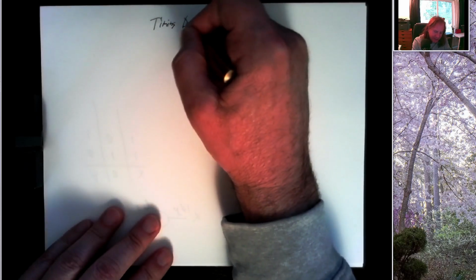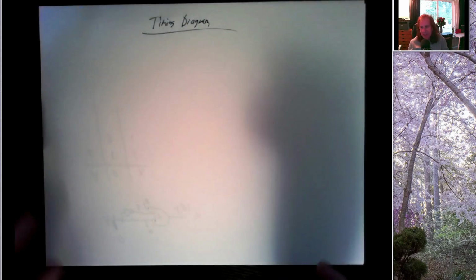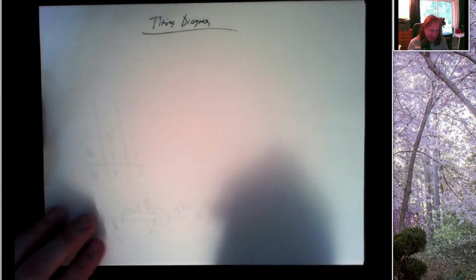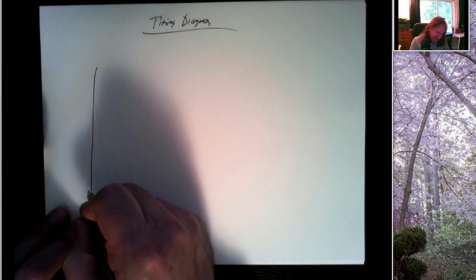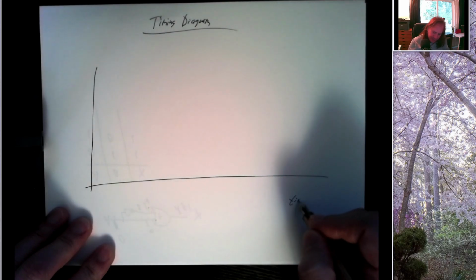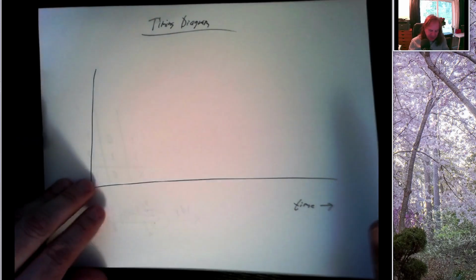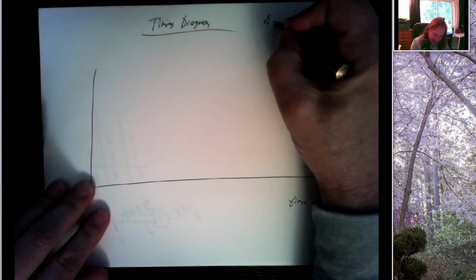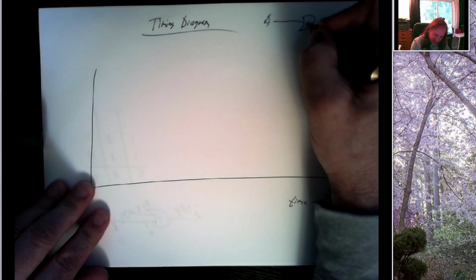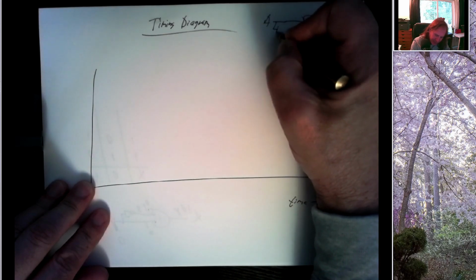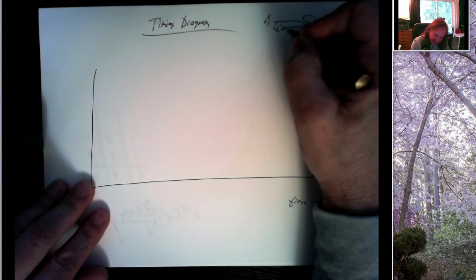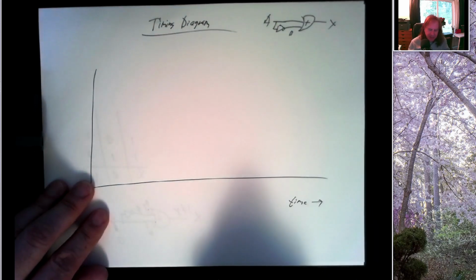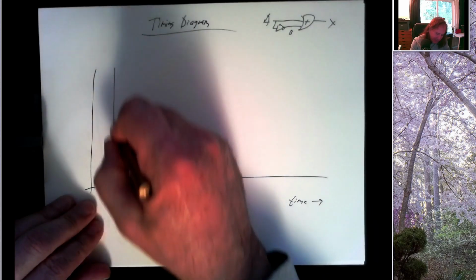All right, so it's helpful to be able to analyze these kinds of situations, and we can do that by using what's called a timing diagram. And a timing diagram basically is like what you see on an oscilloscope, but we draw it ourselves. So we have time running in this direction, and let me redraw our circuit. So this goes into an OR gate. Here's our output X. A goes through an inverter. We'll call the output of the inverter B. And let's see what this does. So let me put some time marks on here.